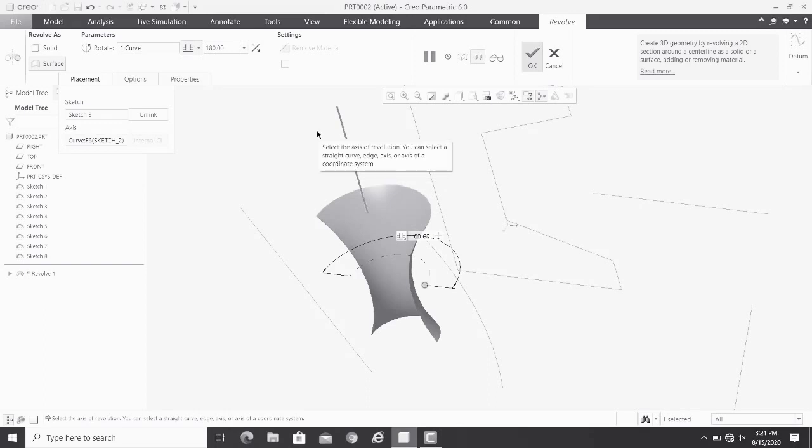Once you revolve an open entity around an axis, then you can switch back to the solid and convert this surface model to a solid model by giving certain thickness to that particular surface. So if I click on the solid mode option, now you have that thickness option available over here, in which you can change that thickness.